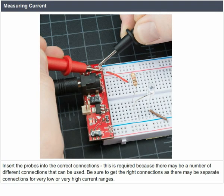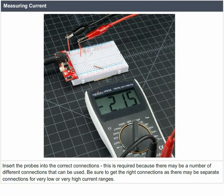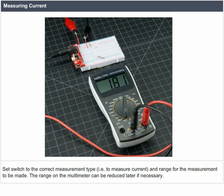Measuring current. Insert the probes into the correct connections. This is required because there may be a number of different connections that can be used. Be sure to get the right connections, as there may be separate connections for very low or very high current ranges. Set the switch to the correct measurement type, that is, to measure current, and the range for the measurement to be made. The range on the multimeter can be reduced later if necessary.